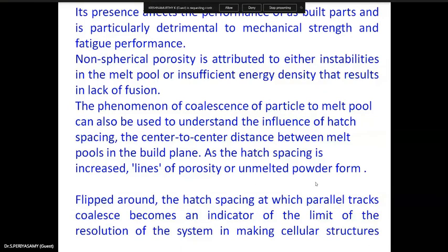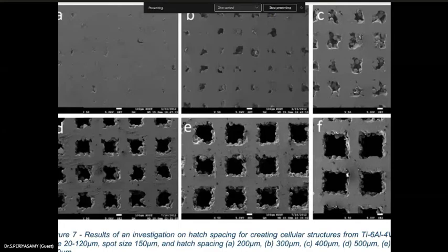In the other cases, you have some pressing. Even you know that casting and forging parts differ. In casting you may have porosity or internal defects, but in forging you are compressing it out, giving a compressive force that skews and recrystallizes the material structure.